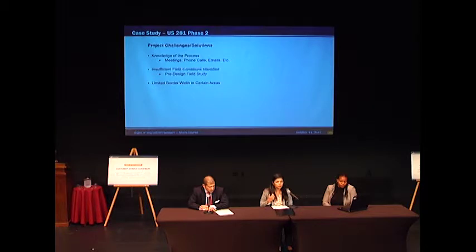One of the ways that we're trying to deal with this issue early on is at the schematic phase, we're asking our consultants to develop proposed utility corridors, especially when we're acquiring right-of-way, so that we're not just guessing, but we're confirming that there is going to be enough room for us to accommodate the utilities.